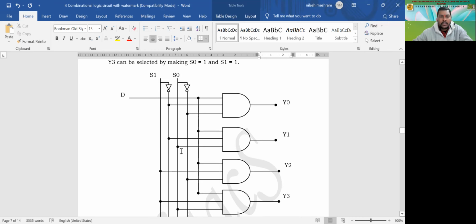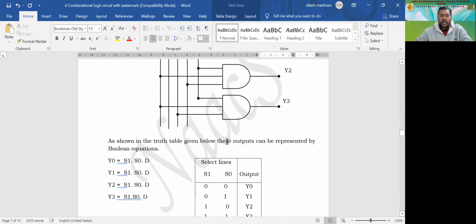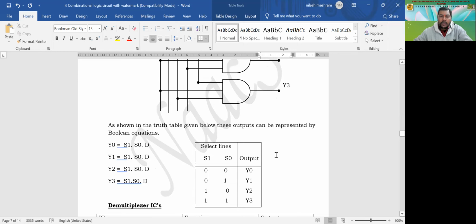We call it demux, and this is a 1:4 demux. We have one input and four outputs, which is why it is called 1:4. At the transmitting end, we require a mux, many inputs to a single line, and at the receiving end we can use this demux circuit to connect the outputs. Earlier it was being used this way, and this is how it gives you the output.